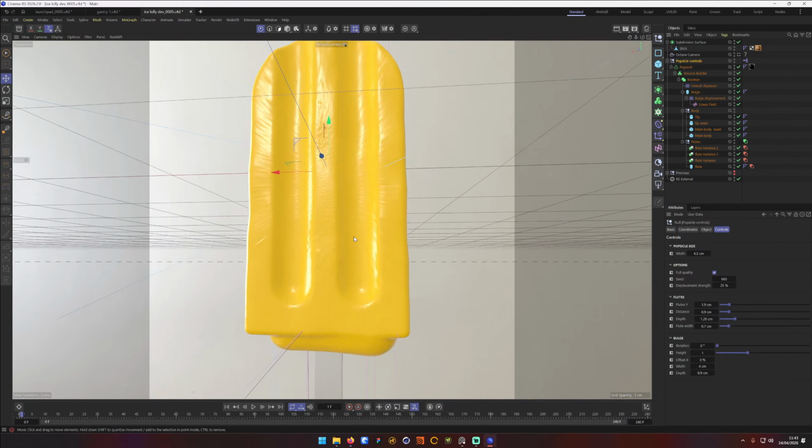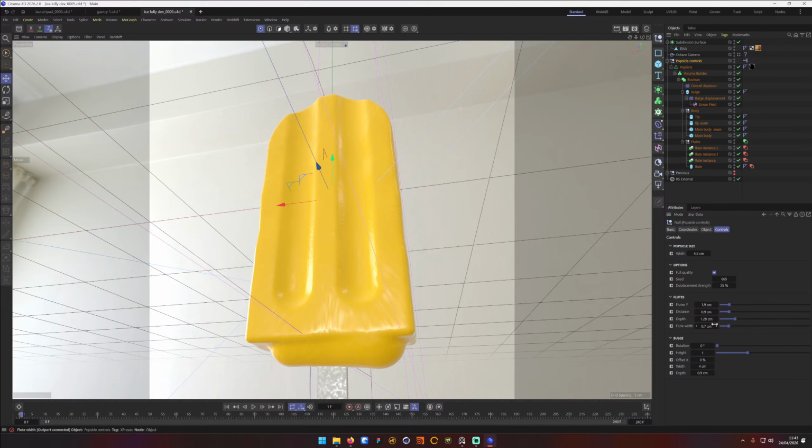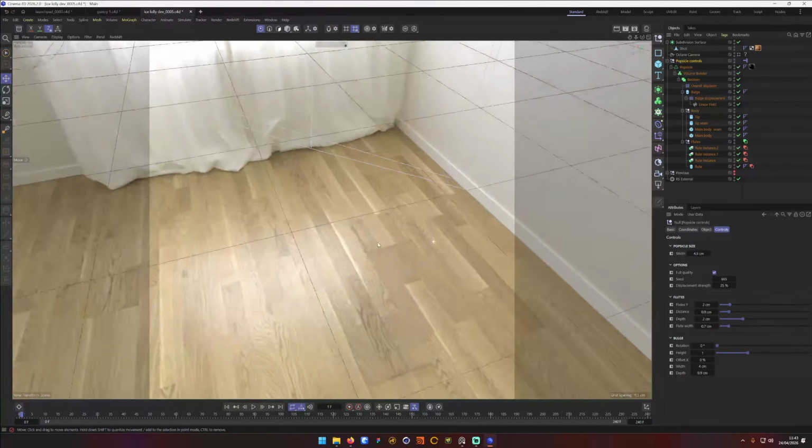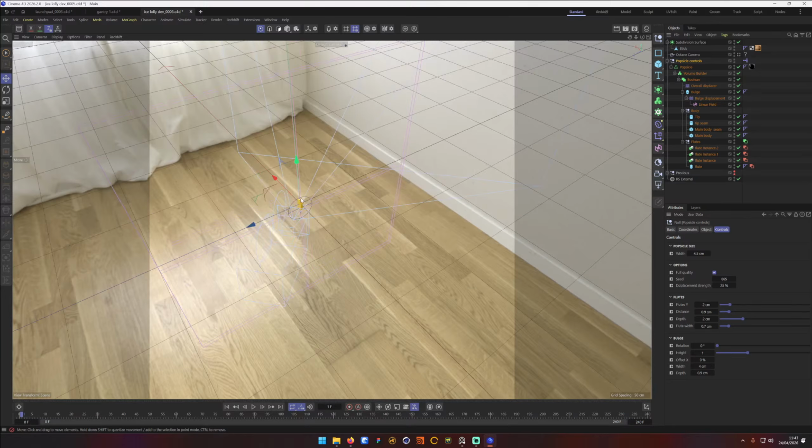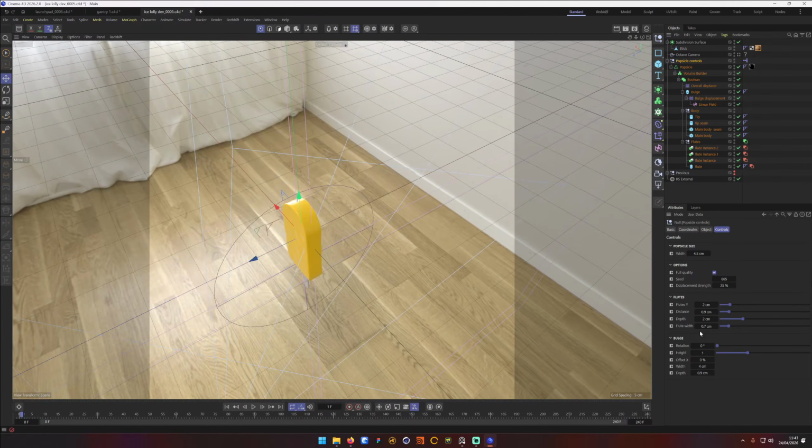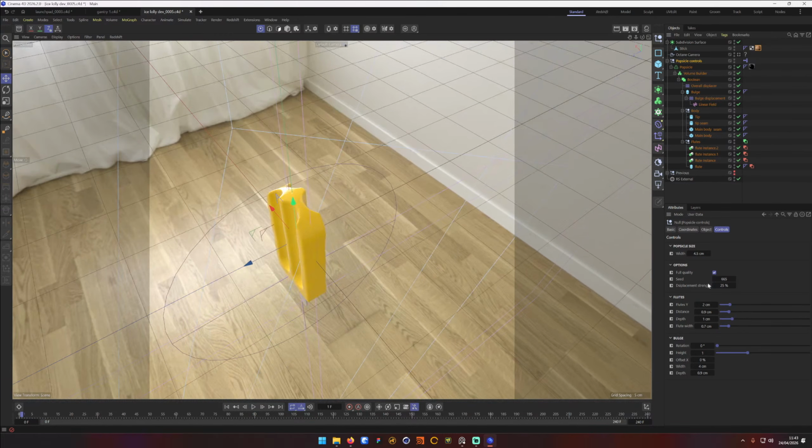So between the variations of this, I can change the depth of the flute distance. Let's make that like 2, whatever. We'll change the depth of those. That's the Y of the flutes. That's how deep they go. So you can vary this. You can also vary this with randomization. Let's undo that. We can make that one like 1 centimeter, which will then push them in deeper. So you can vary this.